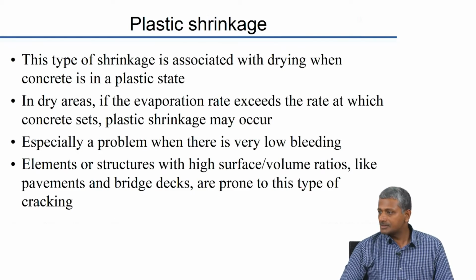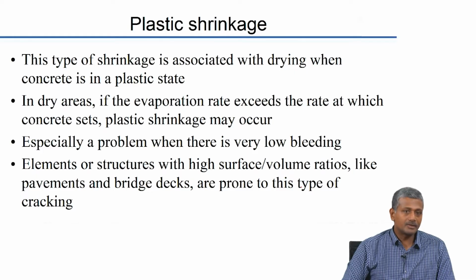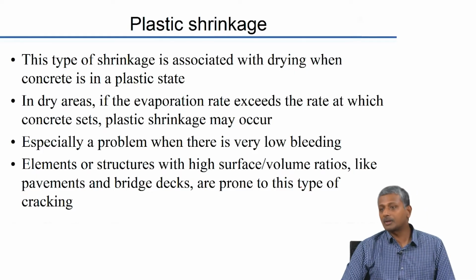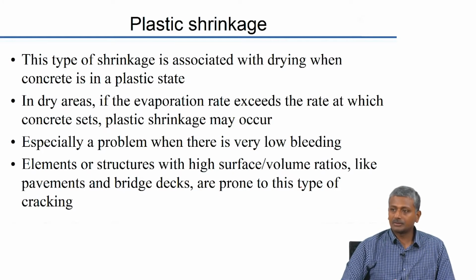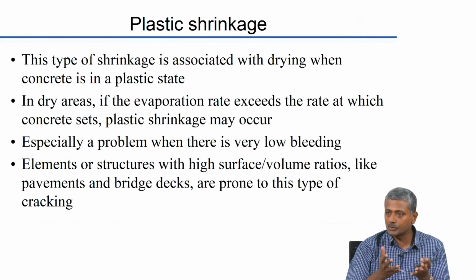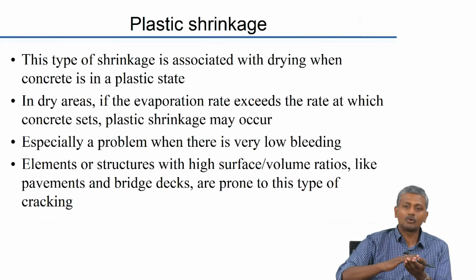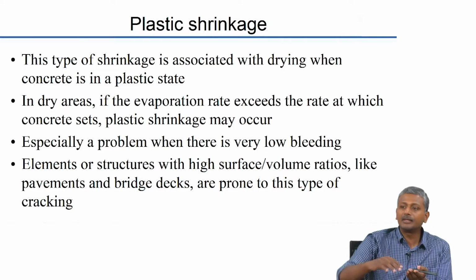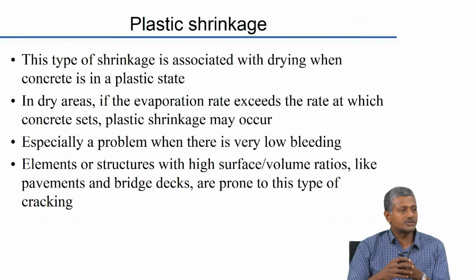Plastic shrinkage is what happens in the early stages of the plastic state. Okay, plastic state implies that concrete is still not hardened completely, it is still moldable, not completely moldable, but it is still subjected to easy deformation if there is any loading on it. So, if the evaporation rate is high from your typically slab type components, because those have very high exposed surface area. The typical concreting operation involves final finishing of the slab, and then after that the curing is only started after 1 day, right, in most construction sites.